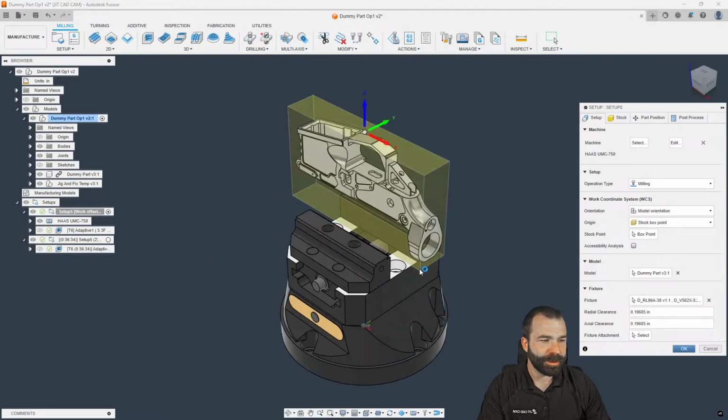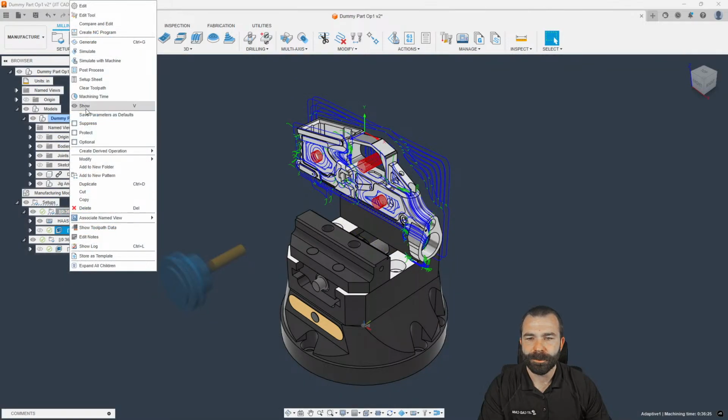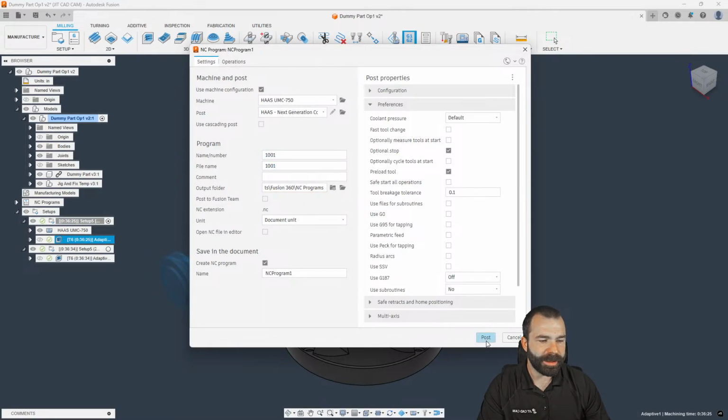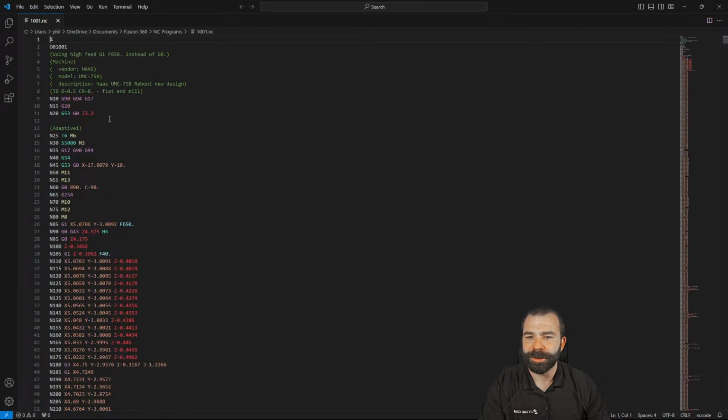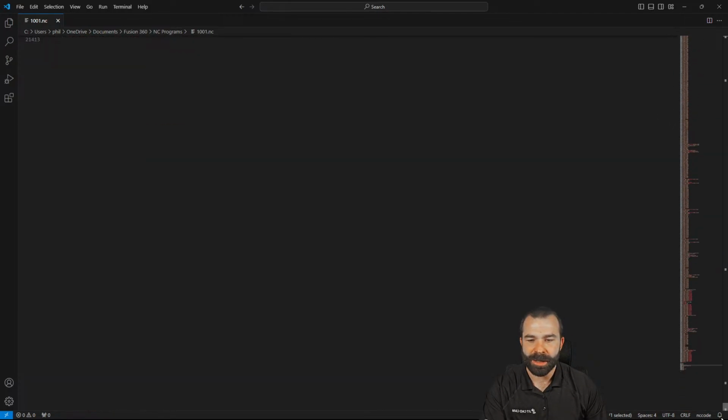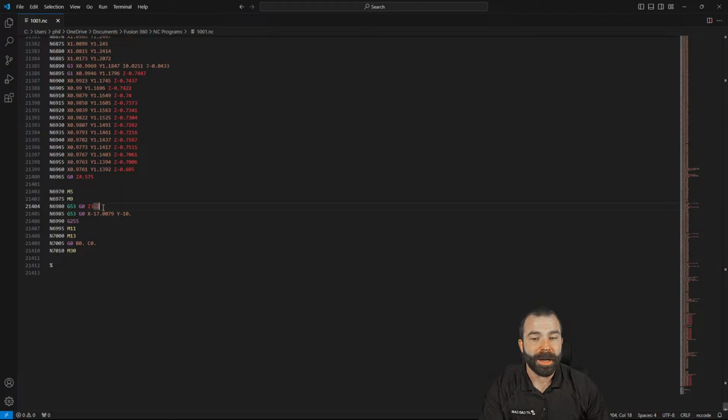So if we go back to what we're doing here on this part, I'm going to post this out. And we're going to go ahead and open that up. And it's going to make me a liar because I probably crashed the machine, and it did not. So if you guys are watching this earlier in this video, we hand edit this G code, but by using machine definition, as Brett was asking and Travis pointed out, we can edit the actual home position on our machine to wherever we want it to be positioned. So as you're seeing, we went ahead and put it 3.2 inches in Z in our G53 callout line.